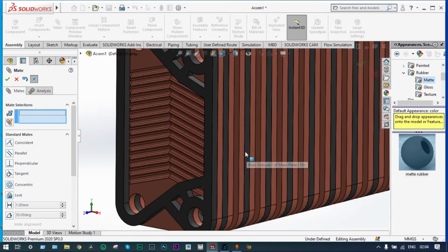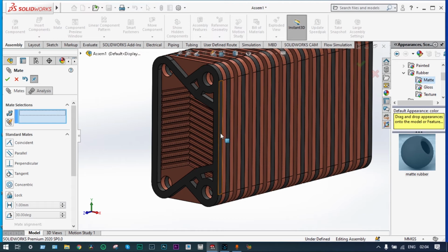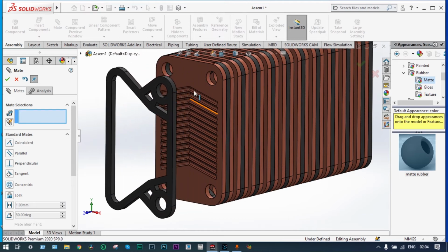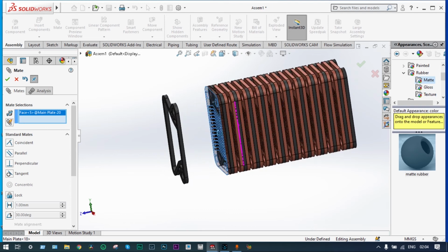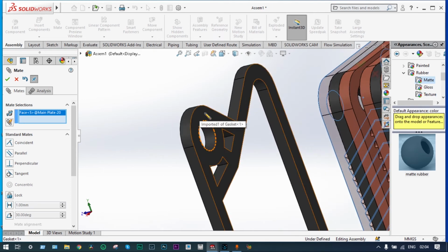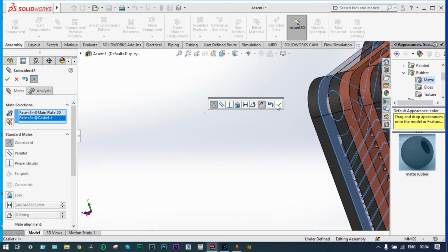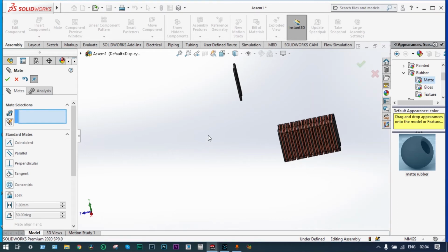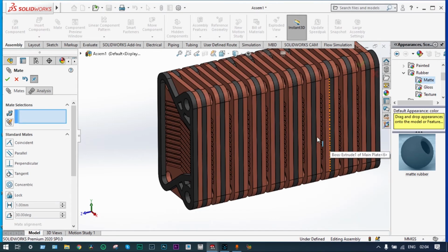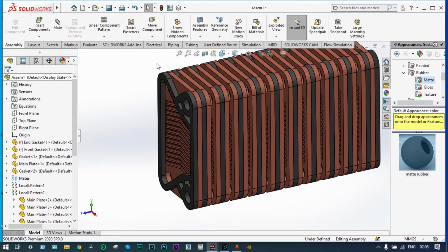Now the third one, that is, the faces in between should have zero distance. Select those faces. Done. So all three constraints have been met. It is done, right? This is actually the backward type gasket. Now that one should be arranged inside these vacant locations, again by using the previous method, that is by using linear component pattern. We can put all these things in the vacant locations.